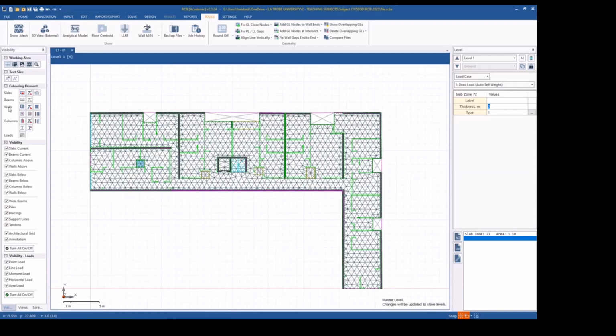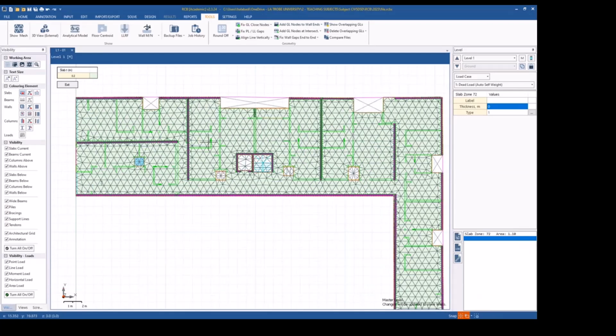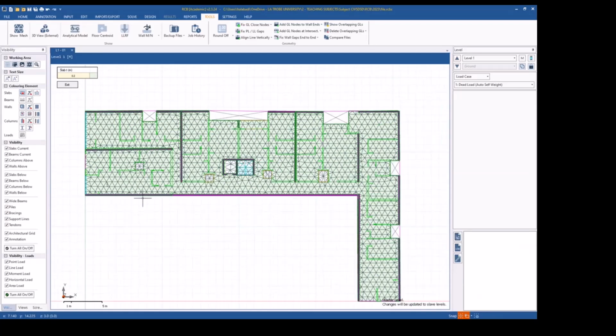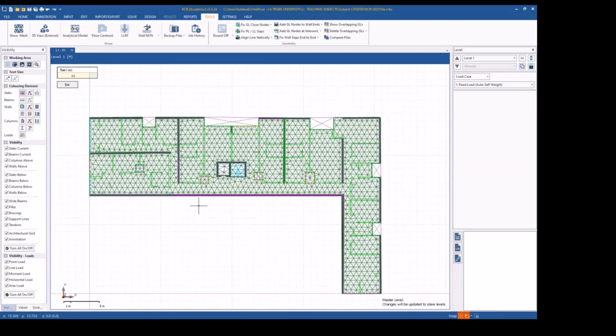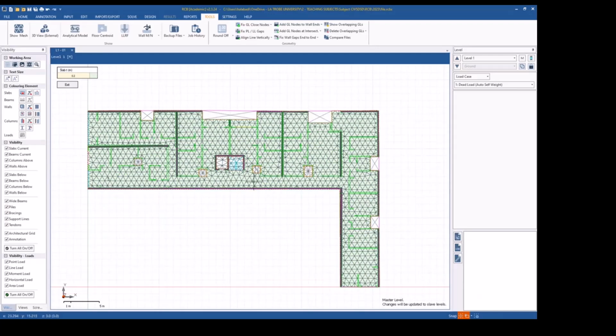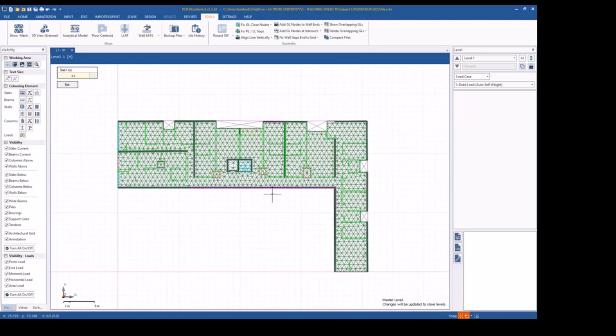There are a lot of nice options here. You can ask the software to show you by colors. Here, if it's a green shade, it is 200. In different projects we may have different thicknesses, different steps, etc. So by now, the concrete elements, slab, columns and walls are set up. What we have to do now is place the loads. It's really easy: placing the loads, dead load and live load.